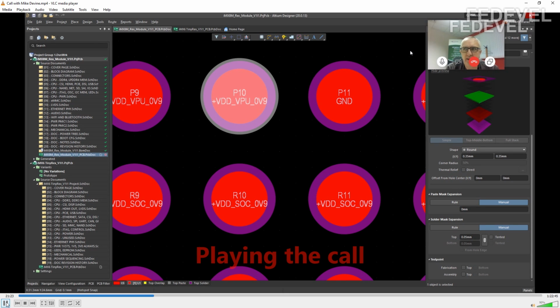Okay. And that is why you've probably seen several white papers on what they call eyebrow cracking, and trying to get designers to stagger the microvias away from the buried vias.